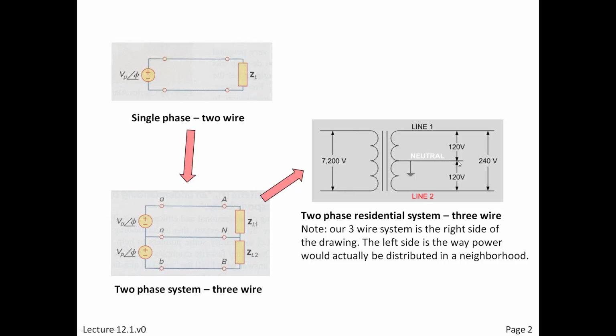If any of those gets loose, breaks free, or is even jiggling around in the wind, this neutral can end up floating, and the net effect will be that these voltages, while they may sum to 240, will flip around. They might be 110 and 130, this kind of thing. They'll add to 240, but they may not be equal, and so that can raise havoc inside the house.